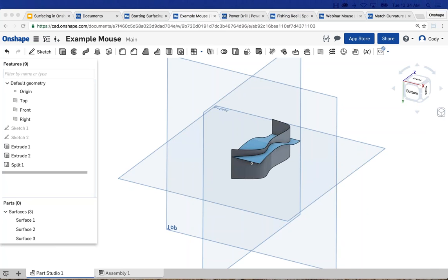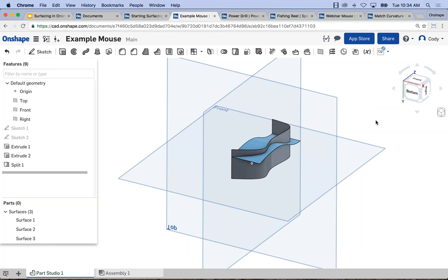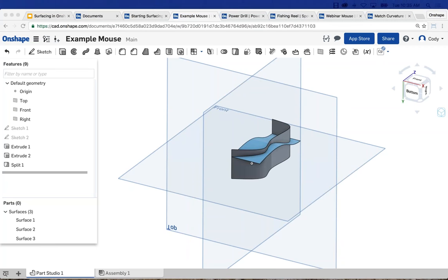Can you demonstrate tangency, normal, and curvature endpoints on conditions in your spline? Can you create greater than G2 curvature continuity in your spline conditions? You can define tangency to other things. Continuous curvature, the tangency would be the closest thing I could think of off the top of my head. And you could, of course, construct straight lines, for instance, and make your handles tangent with those things.